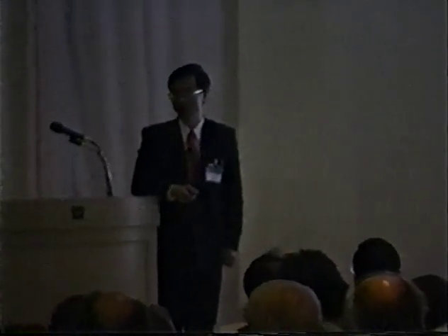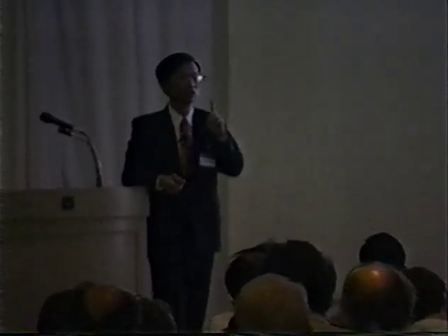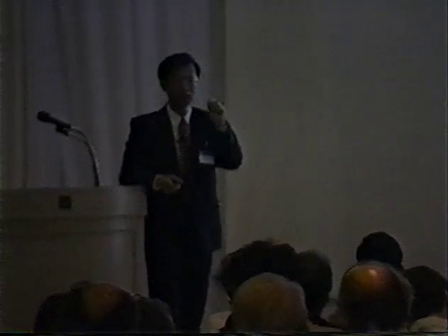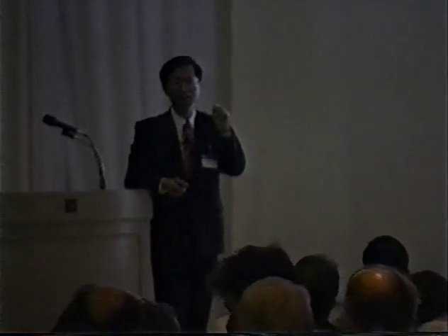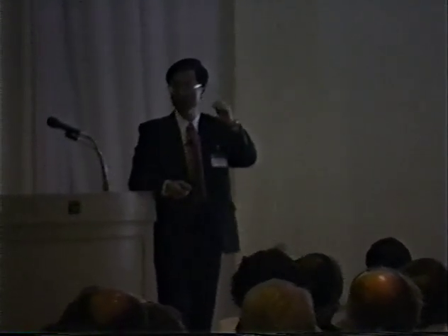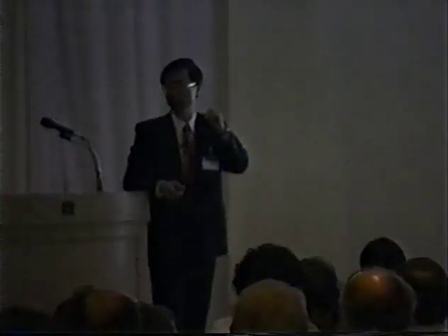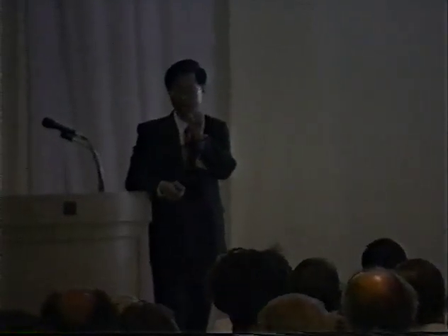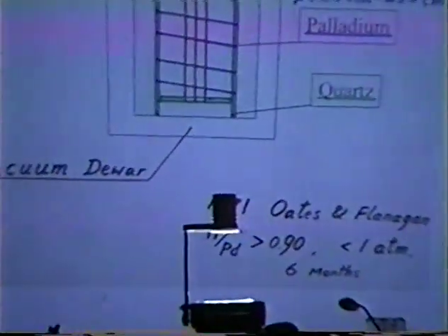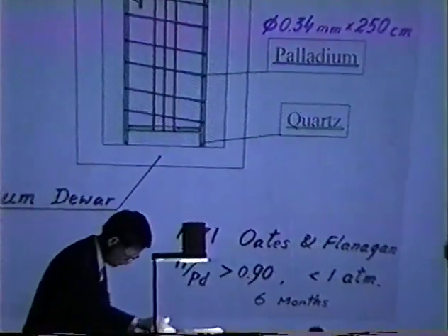I worry about this also because the mass of the hydrogen and of the deuterium differ by a factor of two. So their heat conduction coefficients should be different. However, in my system, the dominant role is the thin wall of the stainless steel dewar. It determines the heat conductivity. So any difference in the gas is minor. If you look at this slope, they are a little bit different.